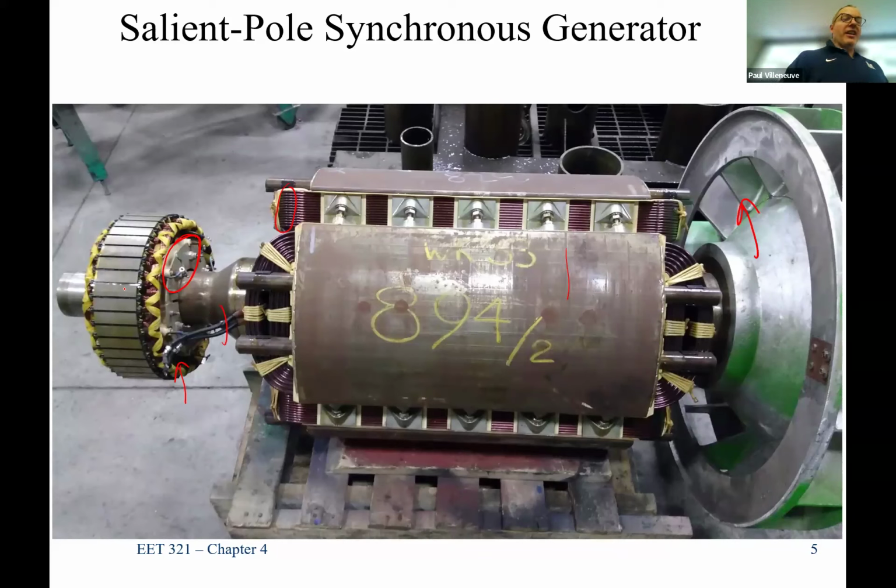Because this is generating AC, right? We know it's going to be spinning around, so we know it's got some AC. You've got to convert that to DC. And how do you do that? That's something spinning, you just tack on some diodes. That's all you need to do. So this one gets its own self-excitation. It actually gets its own power from its little pilot exciter that lives right on the end of the shaft. Not always the most common. Some of them use a different design where they'll get power separately from a different location. I can't remember the application of this one, but this is how they worked it.